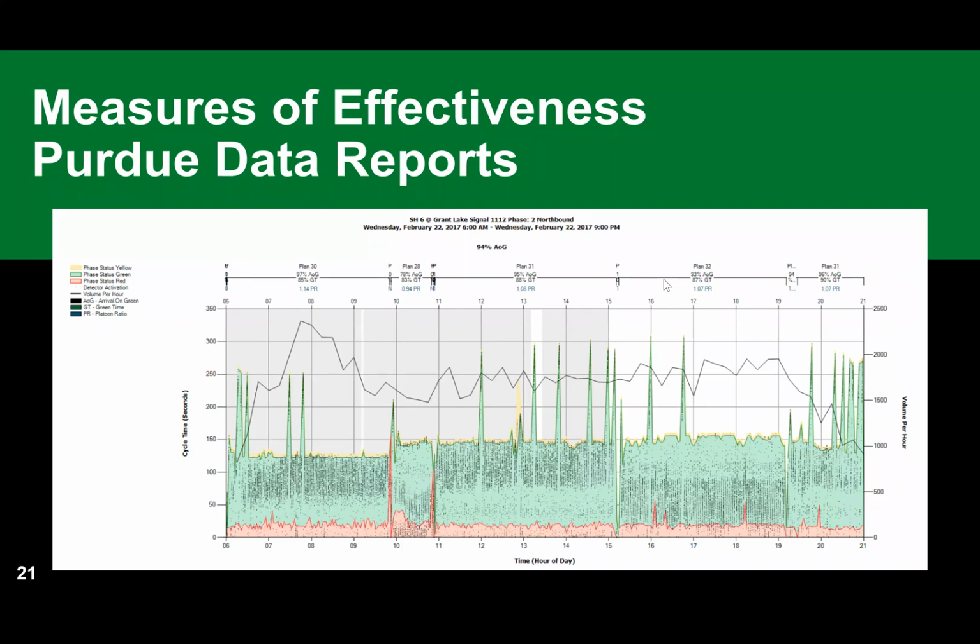All right, Jason, there's one from Nana coming in. When a TSP or pedestrian phase is triggered, does SynchroGreen suspend its optimization until the TSP and pedestrian are finished? No, optimization remains the same because we are able to use a cycle, split, and offset. This is just a transition happening within the system. We're able to pick back up since we're able to adjust cycle by cycle. So the optimization is still there and still runs. Thank you for the question.